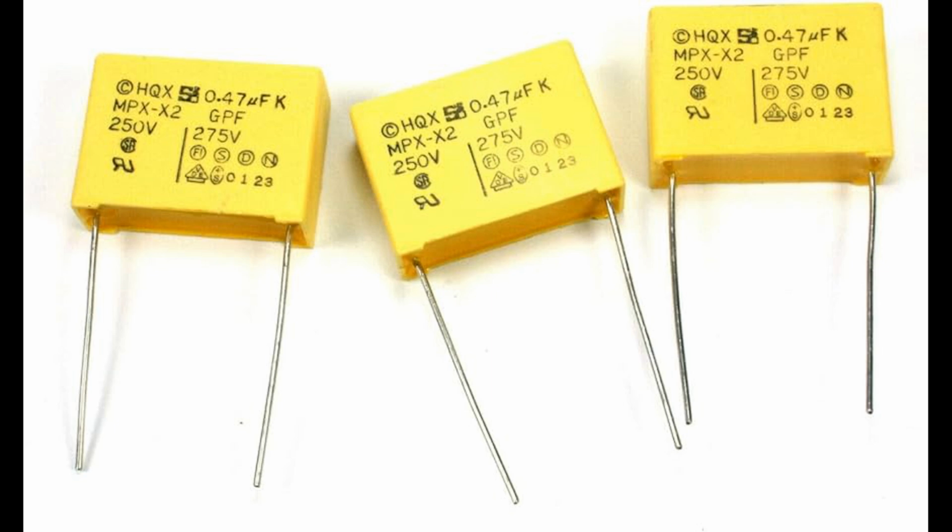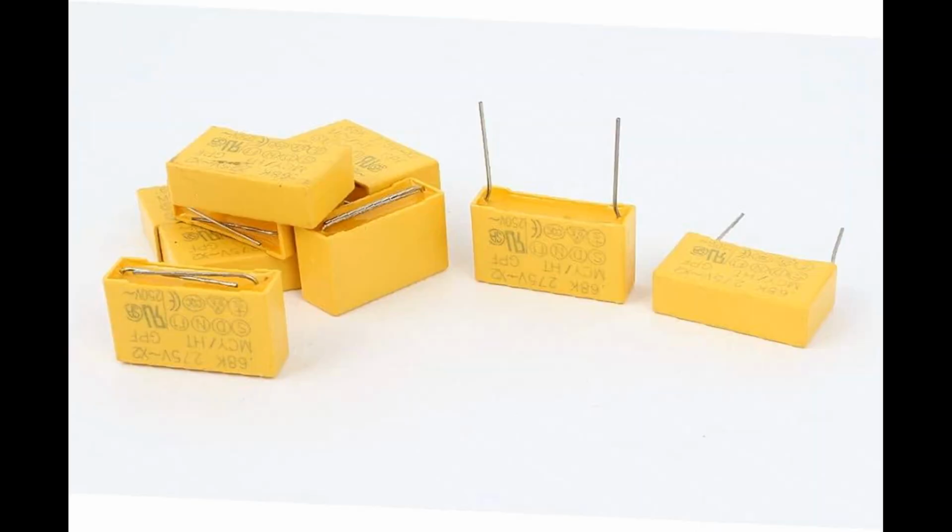10. Low humidity sensitivity. Film capacitors are relatively insensitive to moisture and humidity, making them reliable even in environments that may not be well controlled. This durability in harsh conditions is a significant advantage for outdoor or industrial applications. 11. No degradation over time, no drying out. Unlike electrolytic capacitors, which can dry out over time and lose capacitance, film capacitors maintain their performance characteristics throughout their lifetime, ensuring consistent and reliable operation for extended periods.